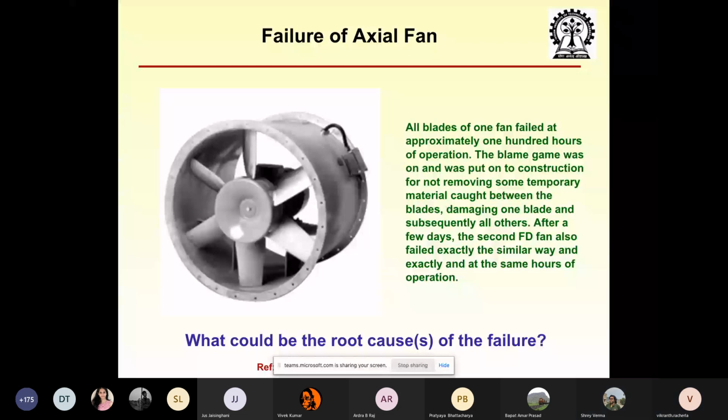Why is it breaking? Because it is a vibration system. It is not getting loaded monotonically in one direction. So it is not just plastic yielding in one direction. It will be like compression, tension, compression, tension. It is being cyclically loaded, and it is experiencing a special condition which results in something called low cycle fatigue. It is fatigue failure, but in each cycle there is a plastic deformation also, and it is this accumulation of plastic deformation which is leading to failure.